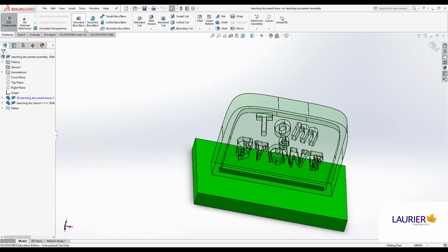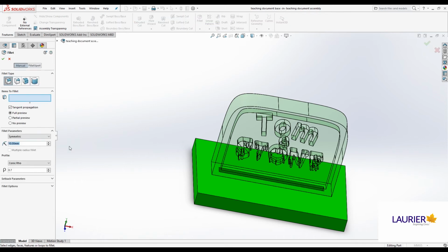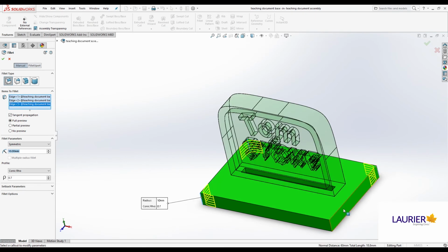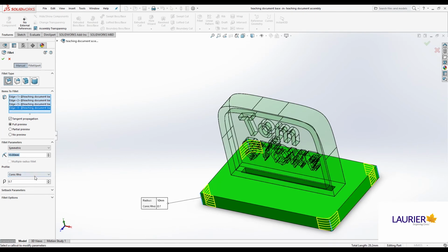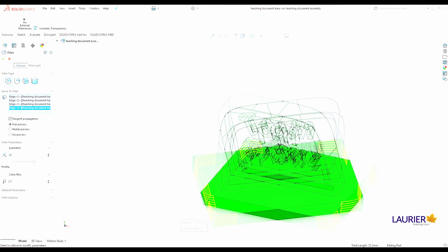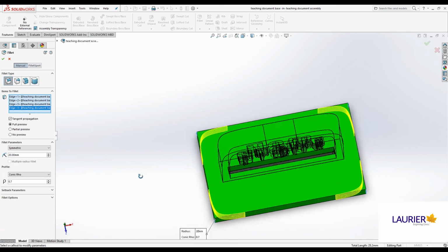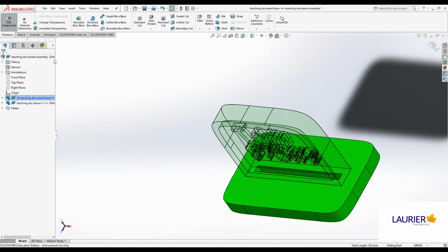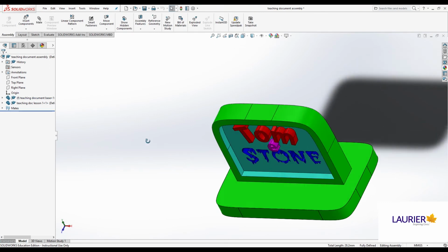Look what comes open, all of our regular 3D tools. So I select Fillet here, and I select my corner edges, and I can put the fillets in the corners. I'll go with 15 because I've got the conic row on the upright, and I think it'll work well together. And that looks pretty good to me. Actually, no, I'll bring it to 20. That looks nice, so I'll say yes, and I'm going to turn off the Edit Component tool. Sure enough, that looks good and the fillets are in place.